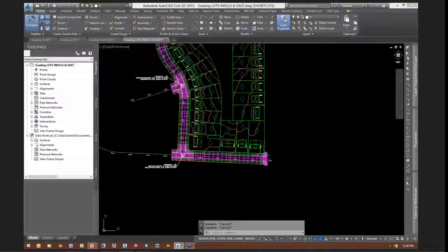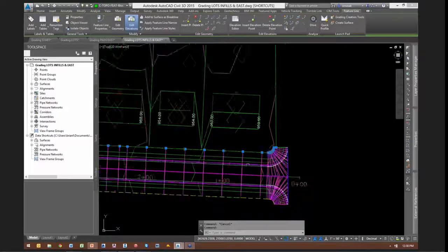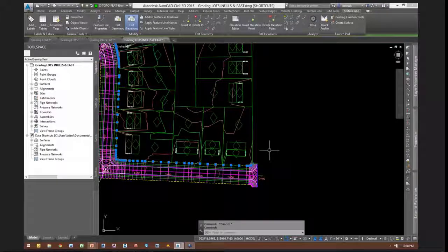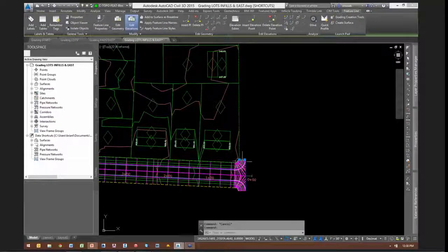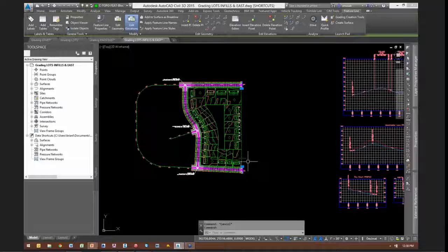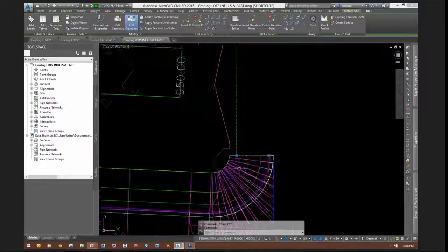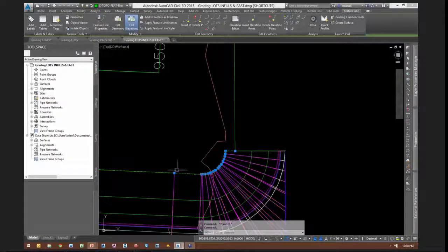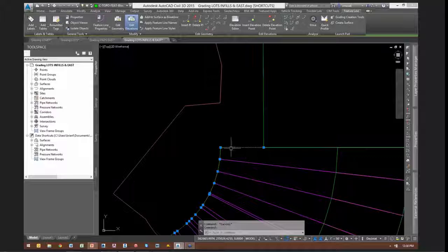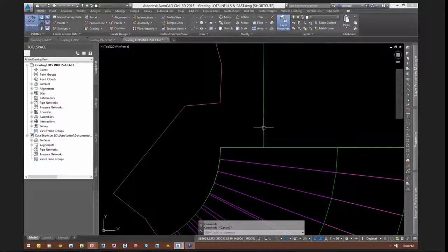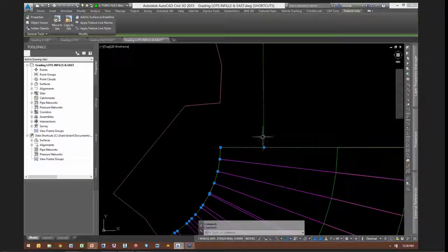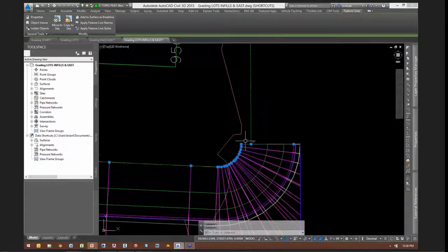Okay. So here's that big feature line again. Okay, one little additional trick I had done is I drew a feature line right along here, right along existing grade. Okay, and then the feature line I extracted from my corridor, I put one little extra piece on it to tie into that feature line. And what that then does is close off this lot right here.